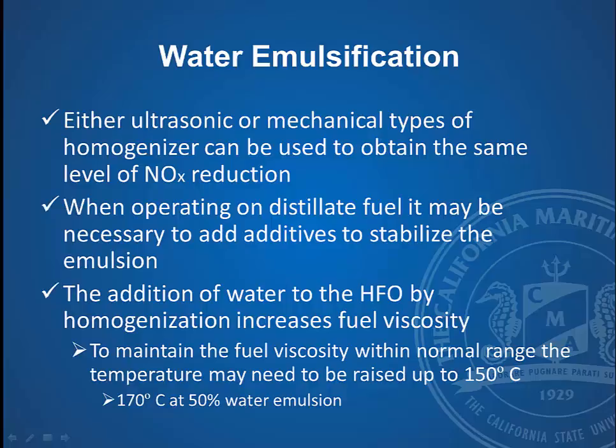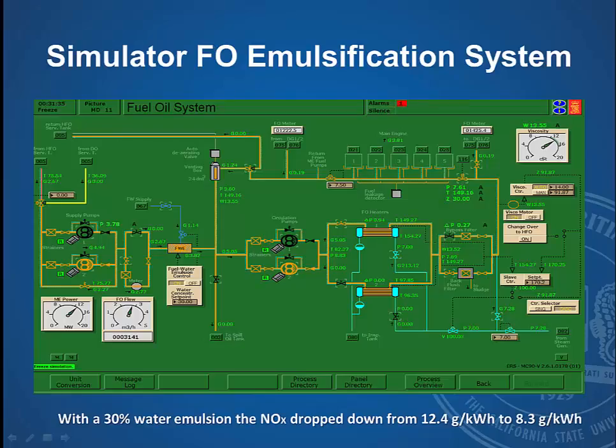But again, it is a concern, and you do have to watch some of the parameters. One of them is that you're at twice the flash point of most of the marine fuels, so there is quite a bit of vapor that's going to be given off by this system.